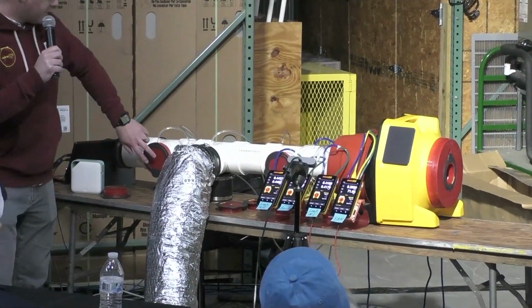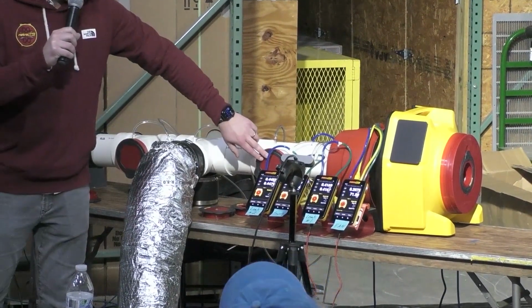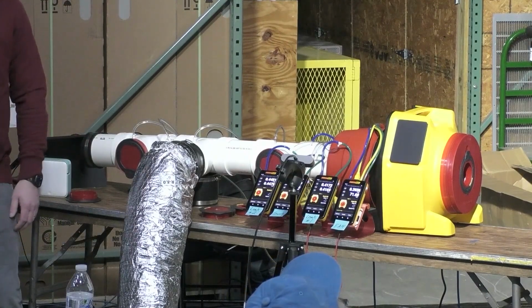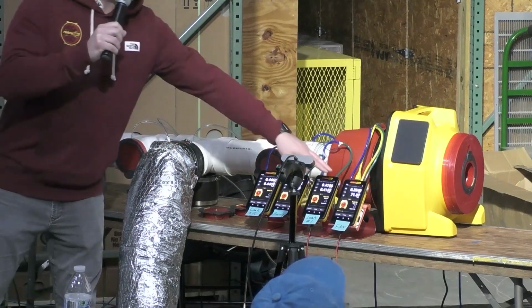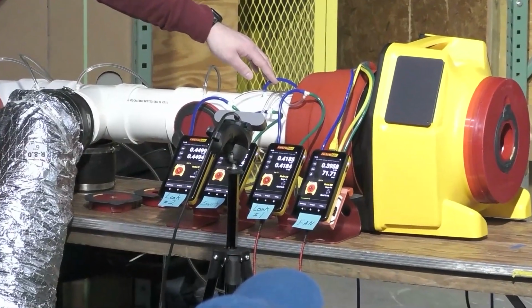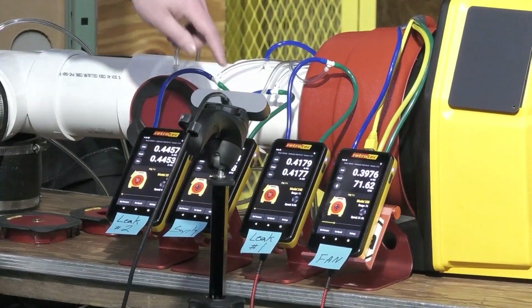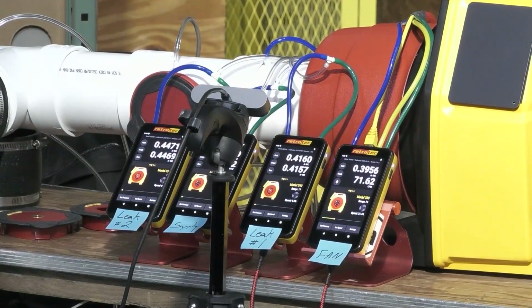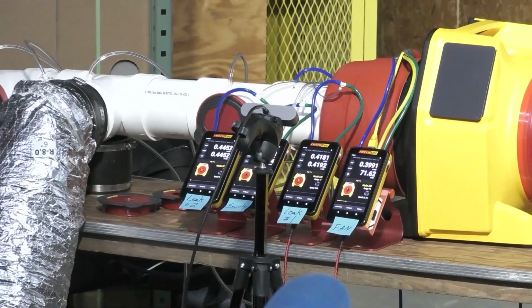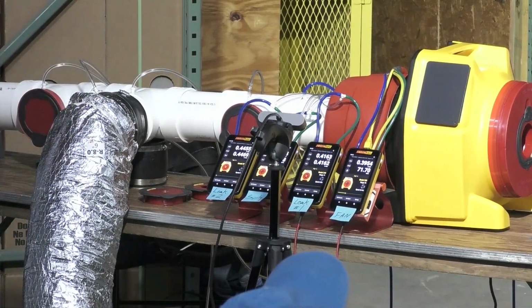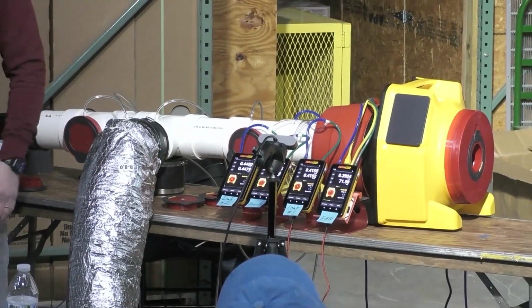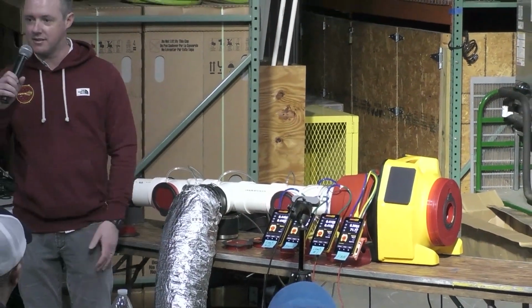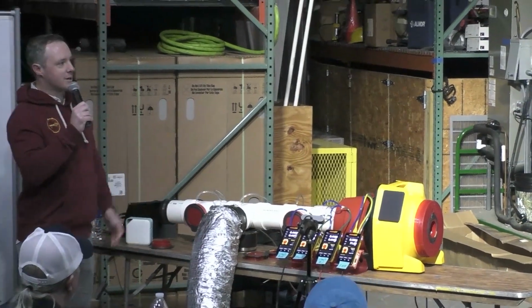Then we added a couple of other spots here where we can add some duct leakage to see what happens to our pressure as we change the duct leakage around in the system. You can see that they're labeled. This first gauge is reading our fan, the total static pressure right here. This gauge is reading leak number 1, here is the supply duct, and then leak number 2 on the end. The cool thing is these 2-channel manometers can read pressure and flow. So we can read the flow going through the supply duct and through the leaks that we simulate. As we change things around, we can see how it changes other things down the line, not just pressure, but flow.